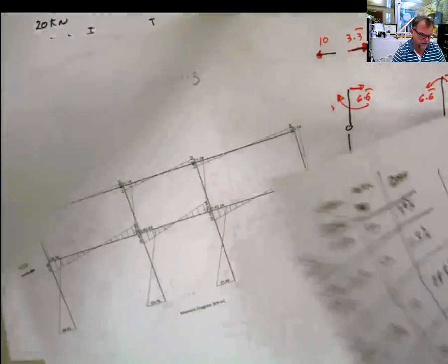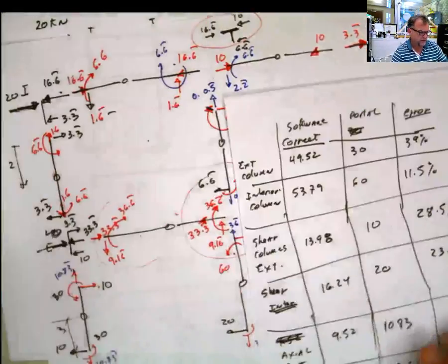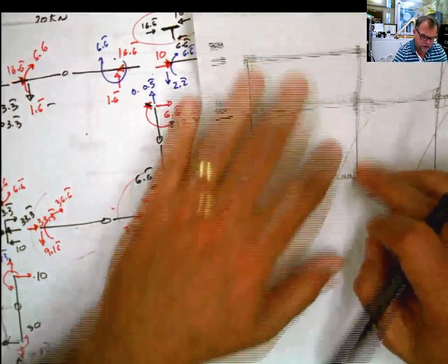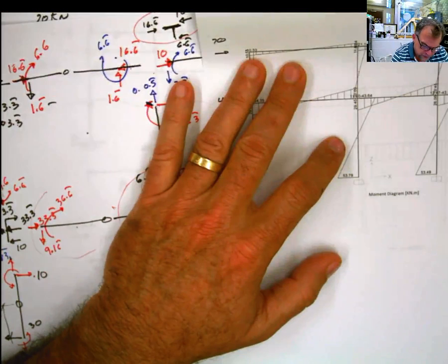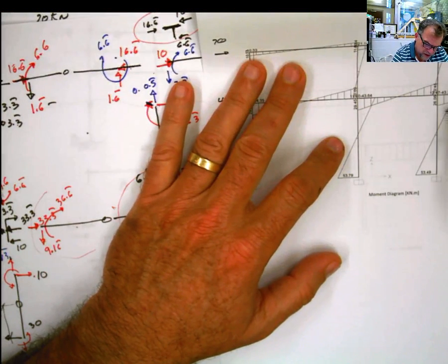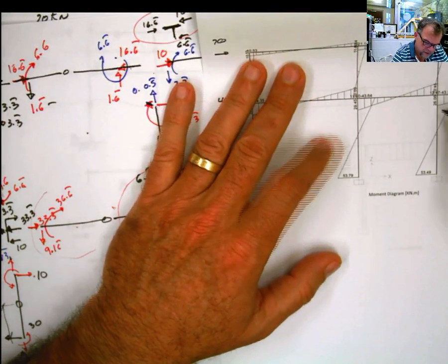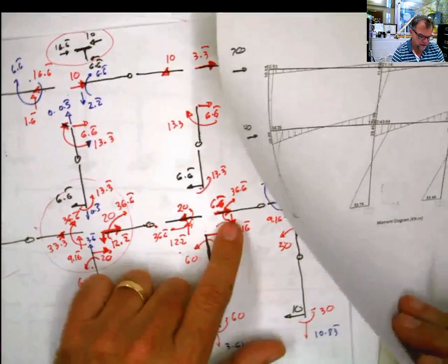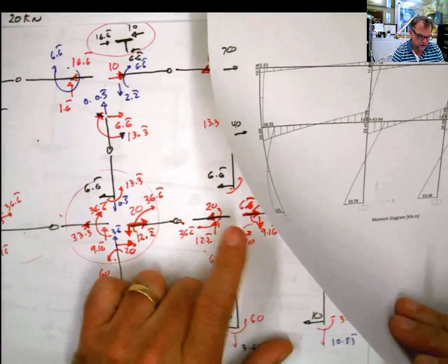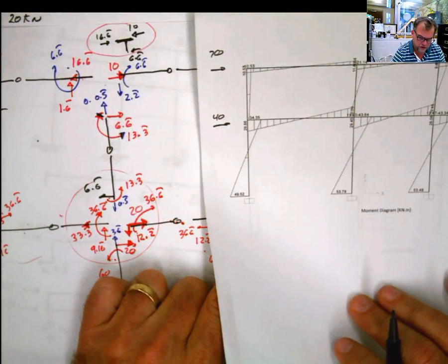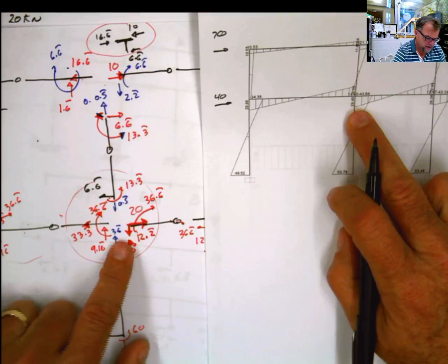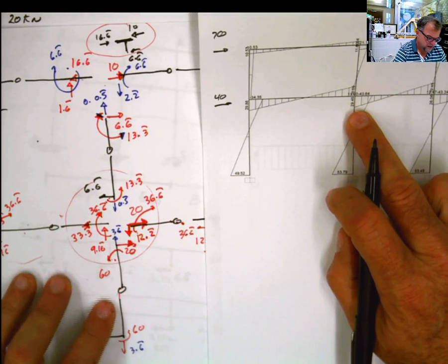One of the things that I didn't check, that I want to check really quick now, is in girders. If we check the moment diagram for the girders, this point in this girder, the value that we have is 26, for example, and the value that we had here was 36. So yeah, the error is also going to be there, and it's going to be kind of considerable. In this case we have 29, and in this case we have 36 in that girder.